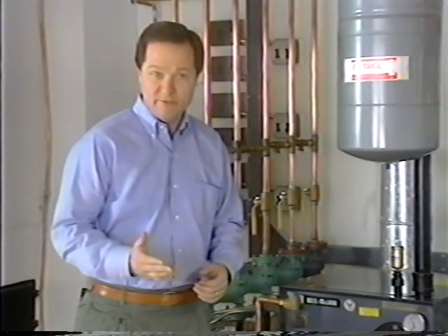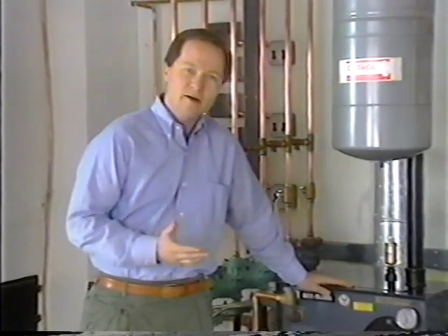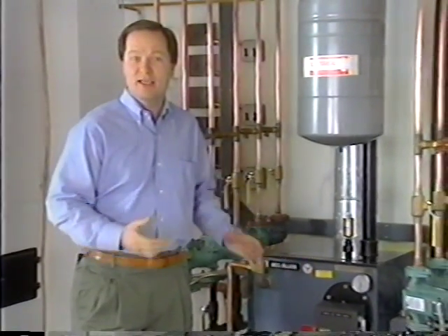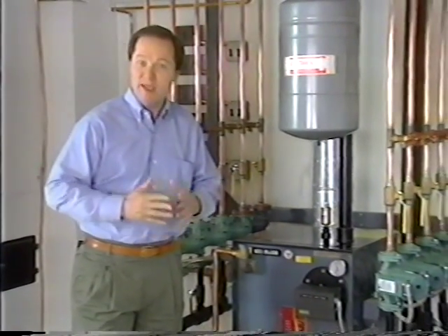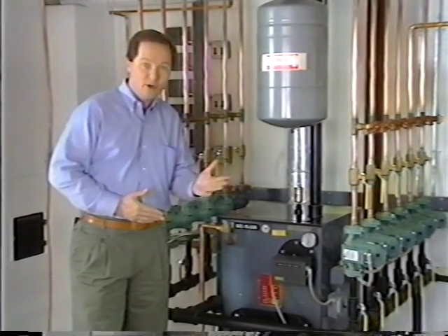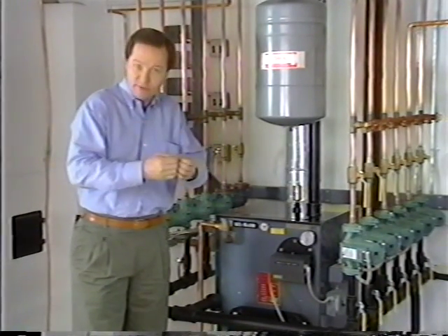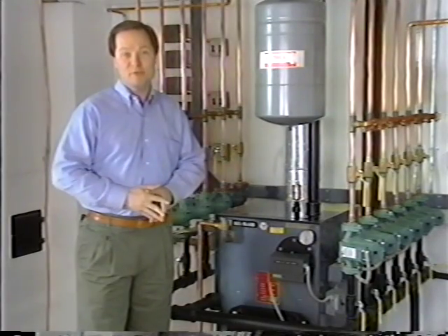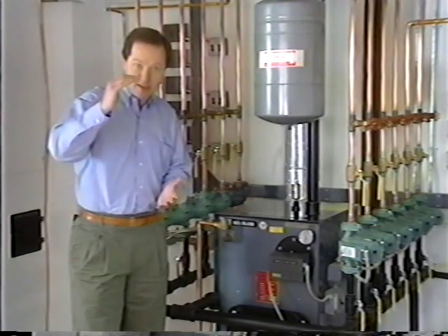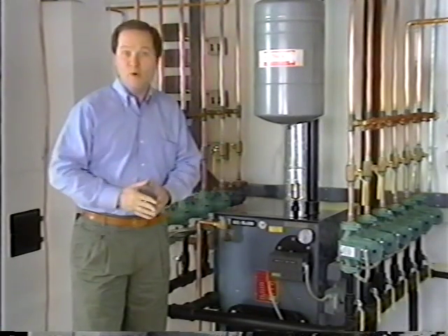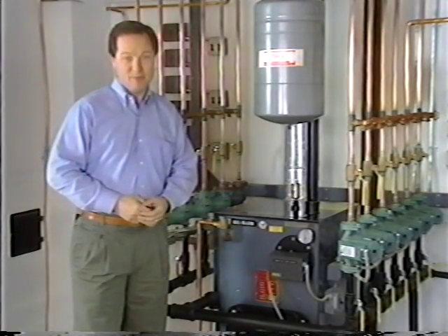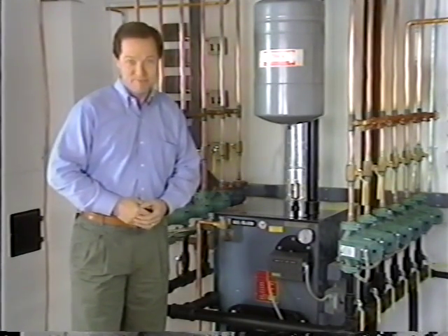One of the major benefits of hydronic heating is that water has the capacity of carrying and retaining a lot of heat. Because of this excellent capacity to retain heat, even when the thermostat is satisfied, the heated water remains in the room terminal and it continues to provide comfort to the room. There are no abrupt temperature changes with a hot water heating system. The temperature difference between a room's ceiling and floor is usually only 1 to 2 degrees with hydronic heating. Up to a 10-degree difference might be experienced with a warm air system.